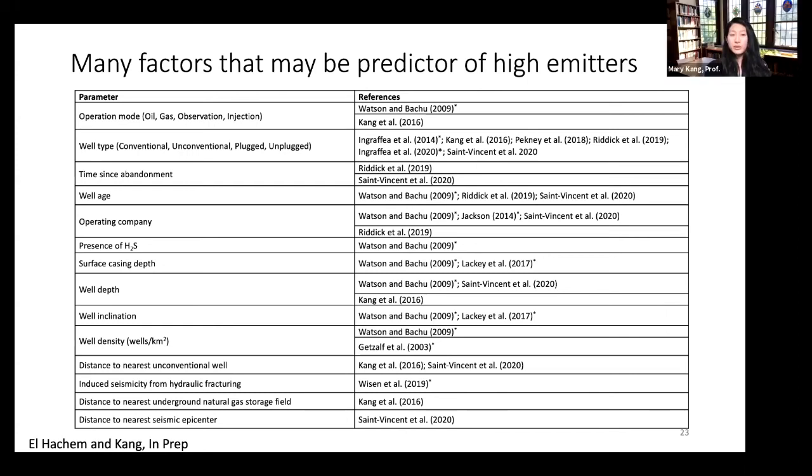Yes, that's totally true. When you have an active well, you could look at surface casing pressures. That's typically what is done in the US. In Canada, you can look at surface casing vent flows to get a good sense. What happens when you abandon? Especially if it's been plugged, you don't have the infrastructure to be able to do those kinds of tests.